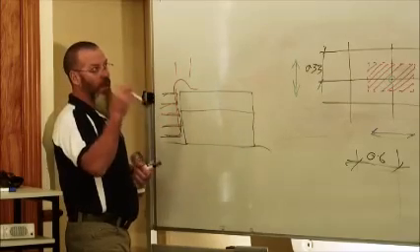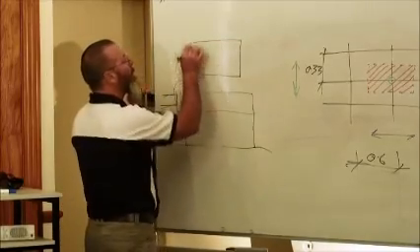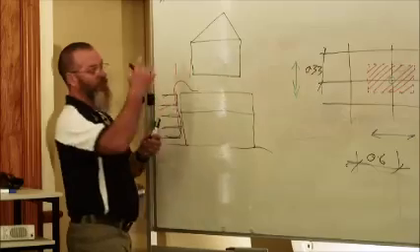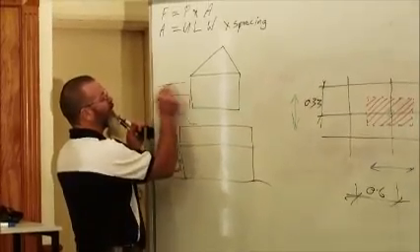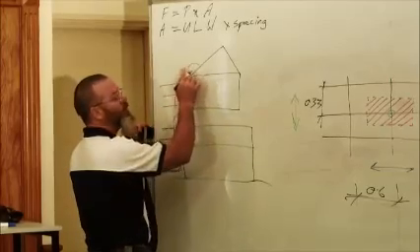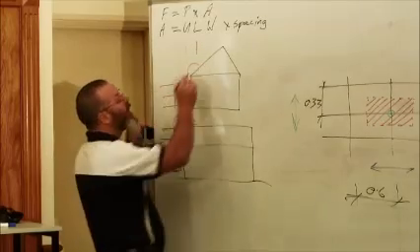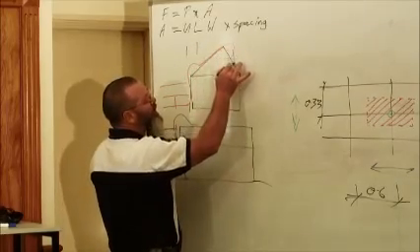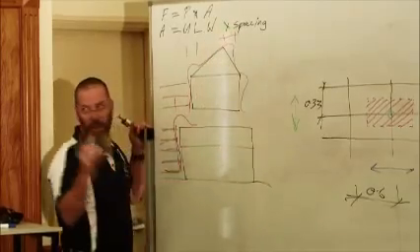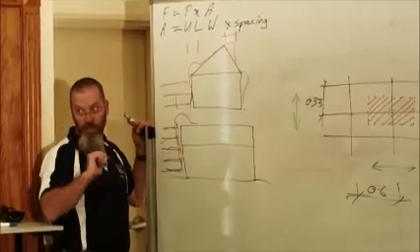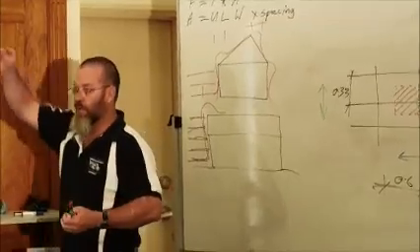You have a look at a stick roof. Badly built stick roof, but it's a stick roof nonetheless. Where you've got the wind arrows coming on the side of the building. So what's actually happening, you're getting a small Bernoulli happening here. So that's an edge within 1.2 metres of the fascia. And then when it comes up the roof, it goes over like that because of this viscosity, over like that and back down. So there's another Bernoulli as well. So that's 1.2 metres at the ridge. And a hip would be exactly the same. As you've got the wind blowing over the side of the hip, it's going to create a Bernoulli on that.